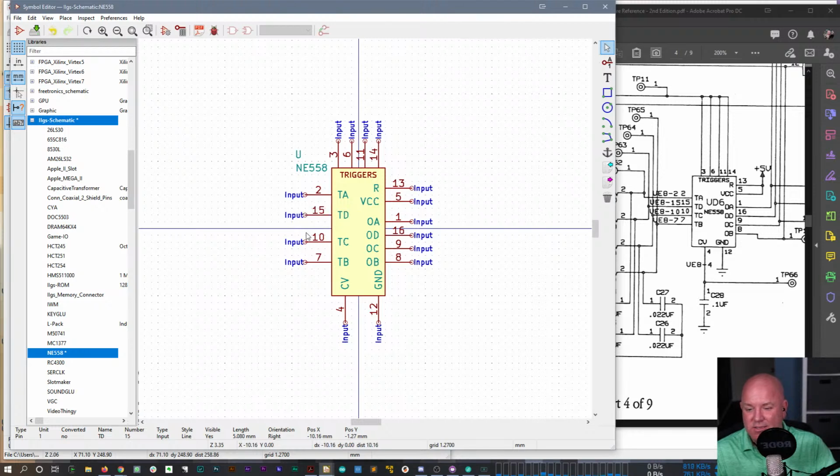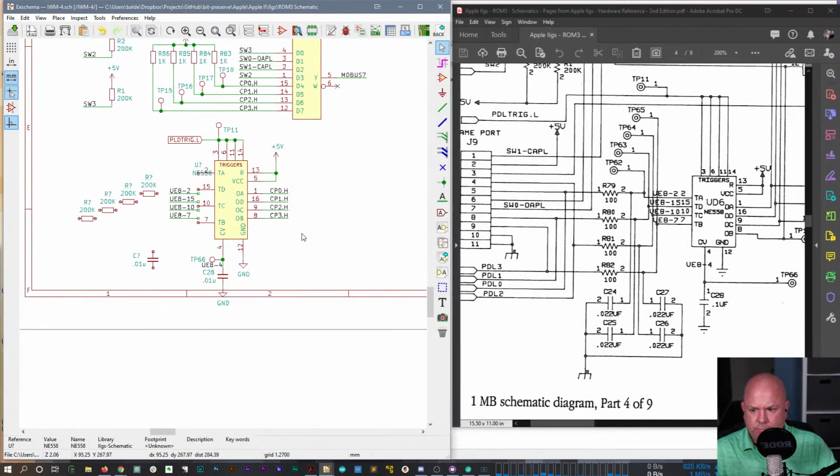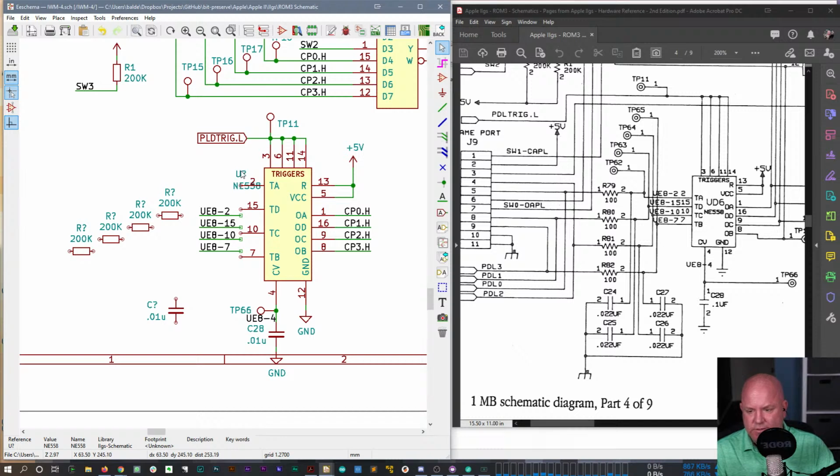The only other area that bugs me is they don't really have a good library or BOM management. What I would really like, and I've seen it I think in Altium, is to define the library of parts that you have. So if I need a 1 microfarad capacitor, instead of selecting the symbol and then saying capacitor 1 microfarad and then finding a part number, when I go into my library, I would actually see the inventory of part numbers that I or my part store, wherever I store my parts, what's available. KiCad's really lacking in that area. In regards to the microwave stuff, the next version addresses some of that already. So I'm glad to see that.